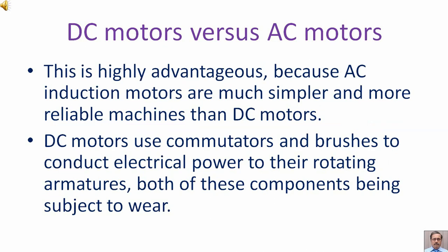This is highly advantageous because AC induction motors are much simpler and more reliable machines than DC motors. DC motors use commutators and brushes to conduct electrical power to their rotating armatures, both of these components being subject to wear.